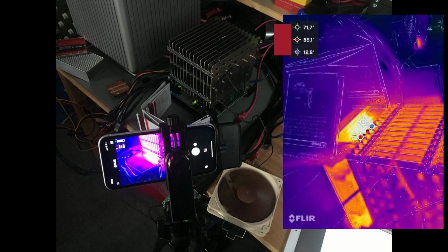So the first one, the crosshair that is shown, is actually the temperature measured at the location where the camera is pointed at. The second part, the crosshair with the red marking, is the hottest spot in the visibility of the infrared camera, and the crosshair with the blue spot is the lowest temperature in the visibility of the infrared camera. Obviously the 10 to 12 degrees that it measures there cannot be correct.